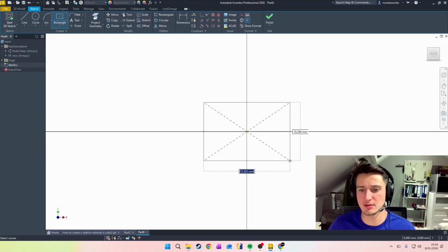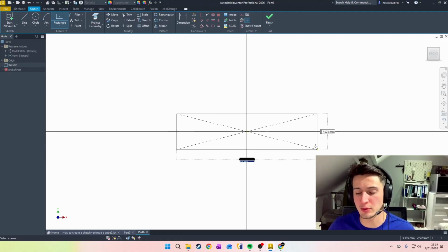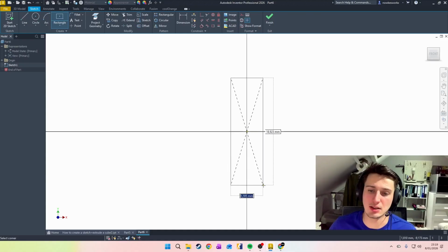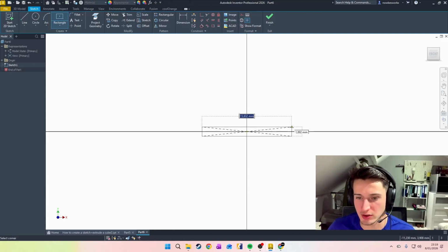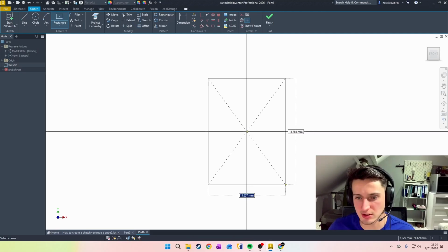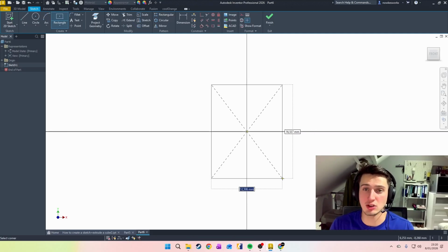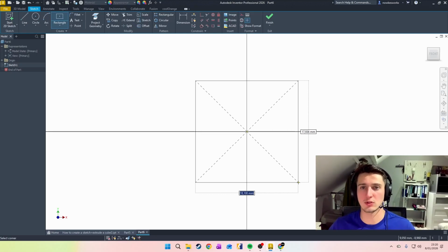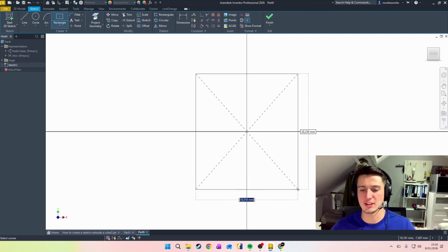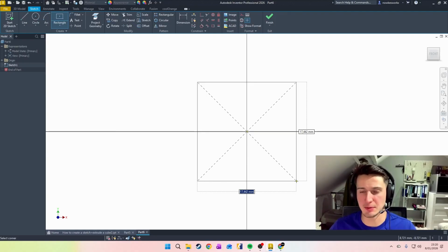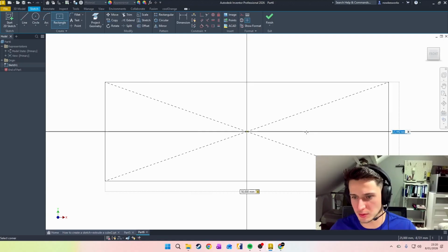So let's click the center, and then we see, if we move it around, that it's all symmetrical. Either way you move it, it's just symmetrical, which makes it, for this situation, easy to adjust in the future. So let's say we want a cube of 50 millimeters by 50 millimeters by 50 millimeters. So let's define. Highlighted in blue, we type 50, then we press tab or we click the other one, then we type 50 again, and then we enter.